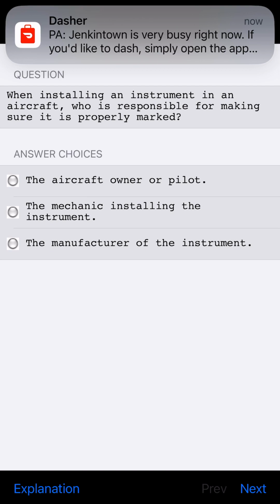Describe the basic operating principle that allows the air cycle system to produce cool air. Hot engine bleed air is cooled in the primary heat exchanger, compressed, and cooled again in the secondary heat exchanger. This air is expanded across a turbine where energy is extracted and the pressure is reduced. This produces a large temperature drop.